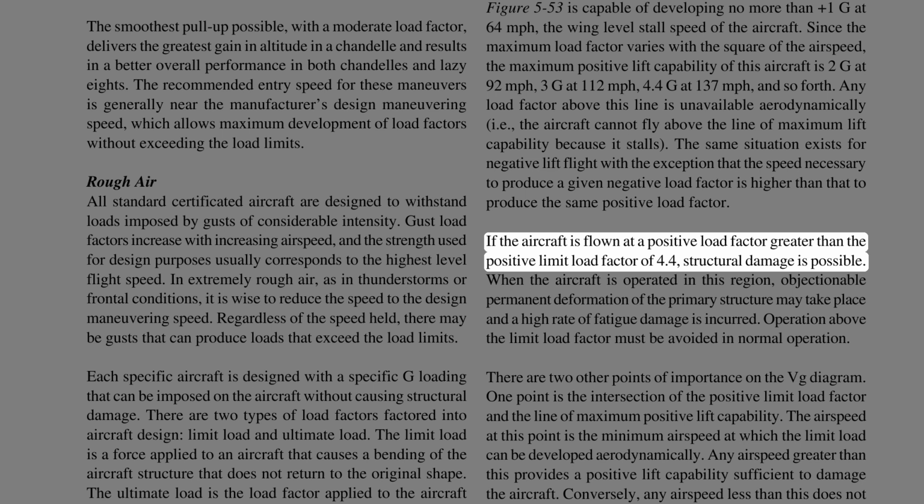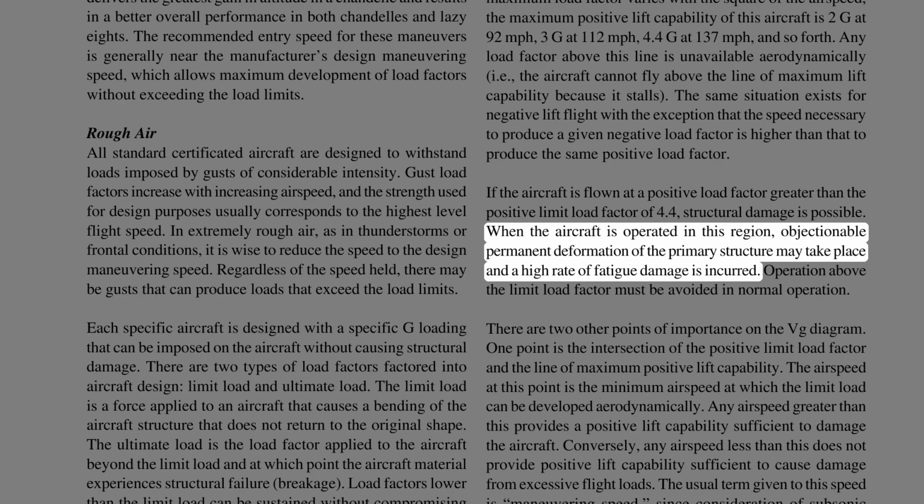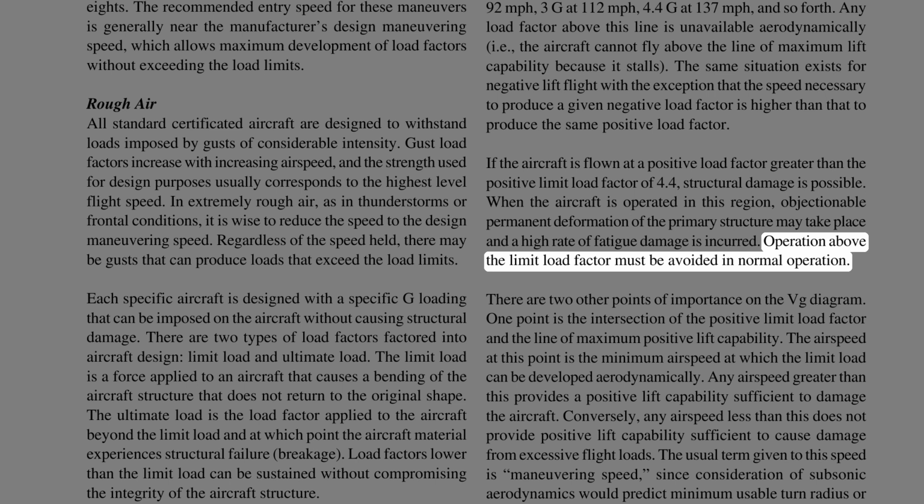If the aircraft is flown at a positive load factor greater than the positive limit load factor of 4.4, structural damage is possible. When the aircraft is operated in this region, objectionable permanent deformation of the primary structure may take place and a high rate of fatigue damage is incurred. Operation above the limit load factor must be avoided in normal operation.